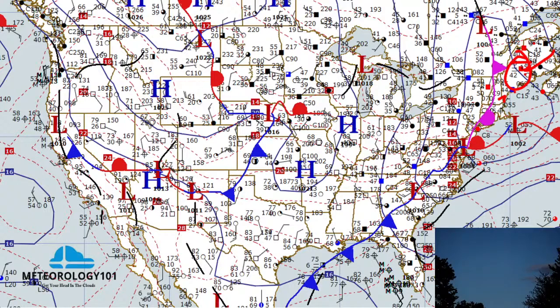Now you don't have to learn how to forecast. You're going to have to learn how to read a METAR or a TAF to find out what time of day you're going to be allowed to fly or not, because you have to stay 400 feet below the clouds. Well, if your clouds are at 400 feet, you're less than 1,000 feet. You want to know how high you can fly that drone. The max height on a drone is 400 feet above ground level. So if the ceilings are already below 1,000, then you need to know what level they are, so you know how high you can fly that drone.